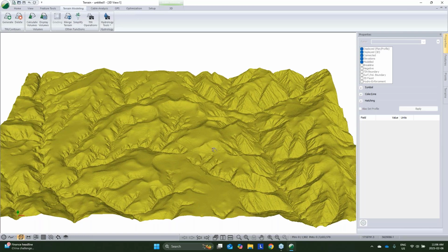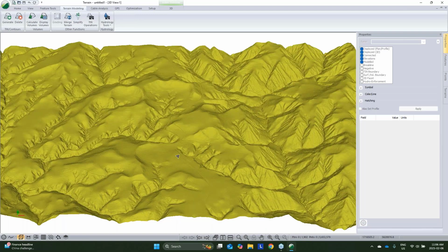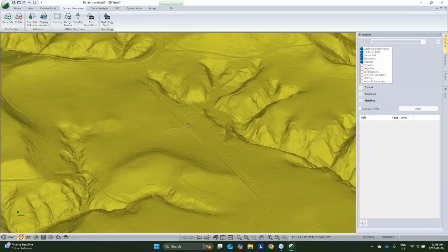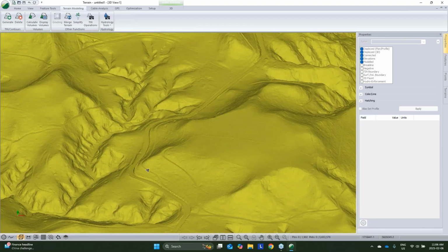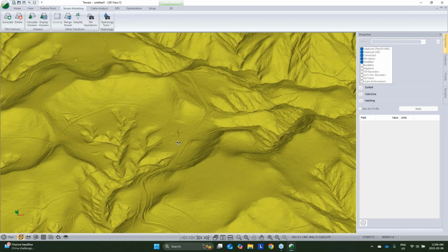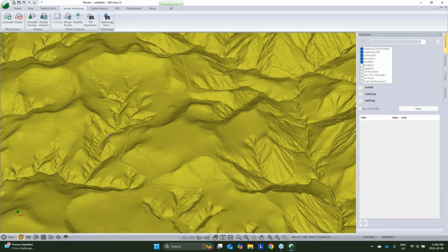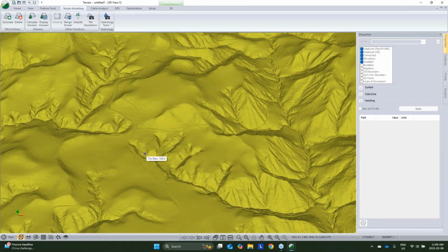Yeah. And so I calculated our TIN surface. So here we can see, rather than just having that surveyed strip of topo, we've got basically a whole landscape with a lot of stuff going on. Now this example project that we're going to deal with, I've got this existing road here, and it's crossing some relatively complex terrain. Problem here is that as it's wiggling through these hills and avoiding these gullied creeks, users have to slow down too much.